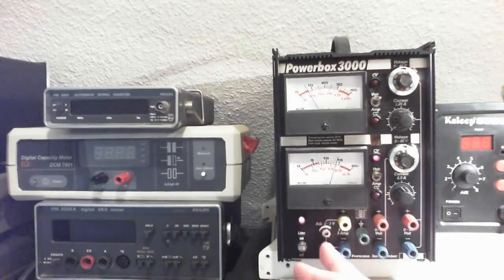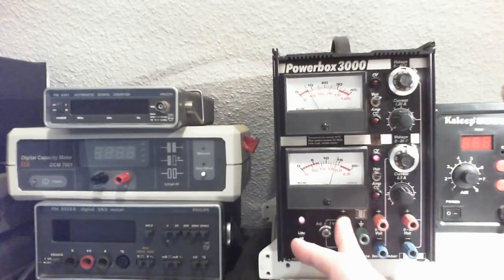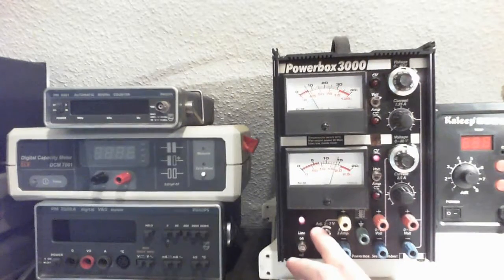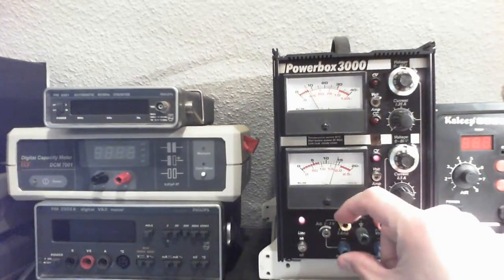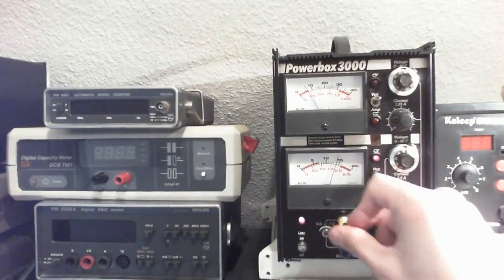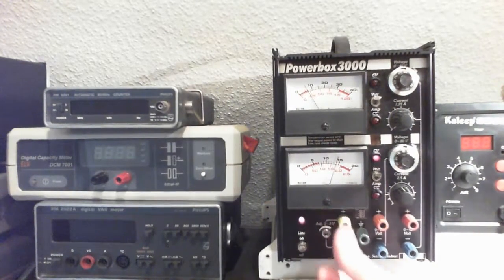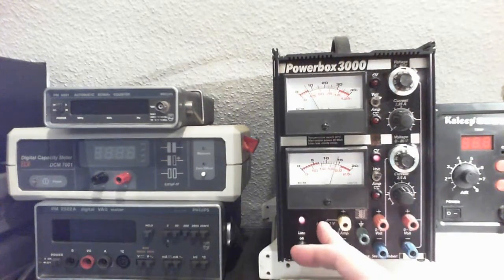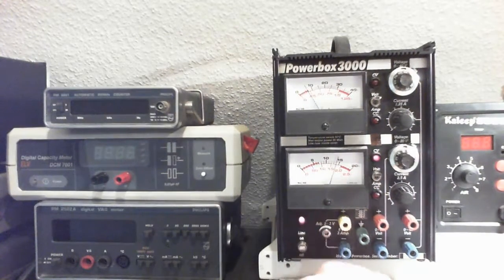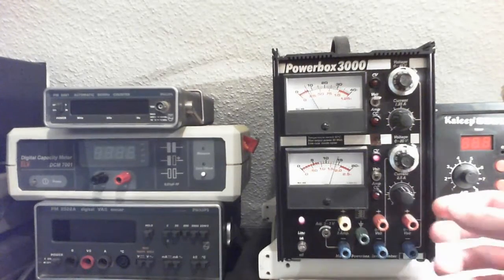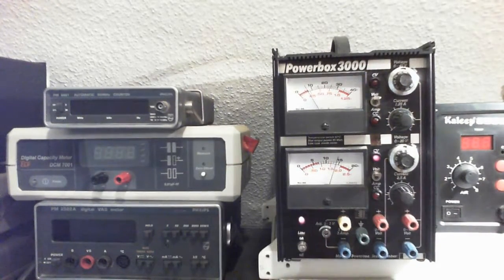And then, for example, this power supply has another rail here. You couldn't call it a rail. It's just some adjustable output, 3 to 7 volts, for example. This is, for example, if you're working on a low power circuit, like a microcontroller or a small circuit that doesn't need much current. You can use a small screwdriver to turn this pot in here, and then you can adjust this voltage, and then of course you can use this voltage for some circuit.